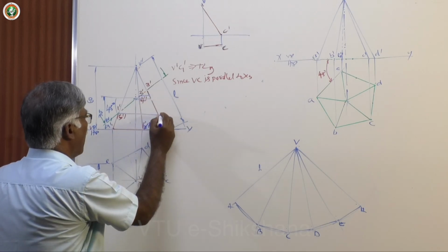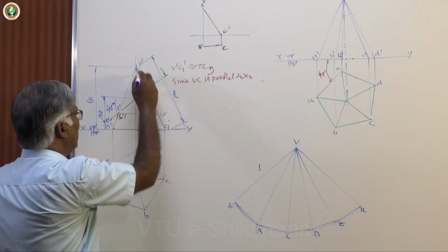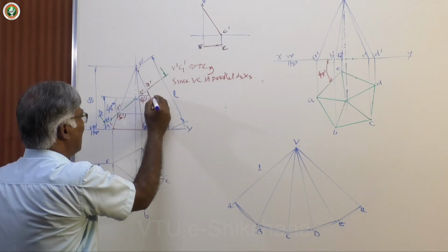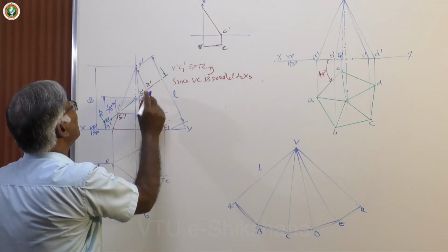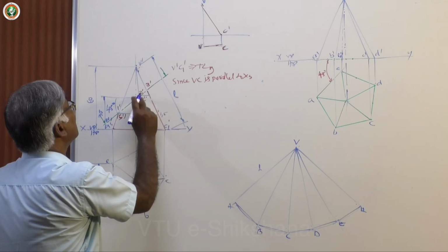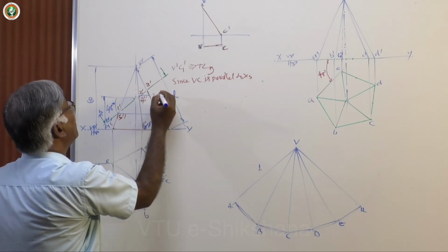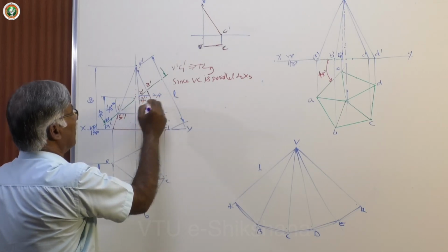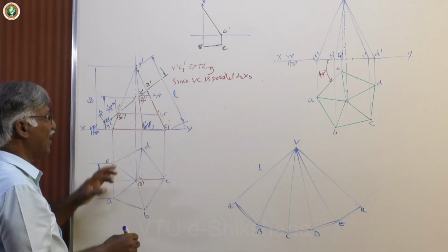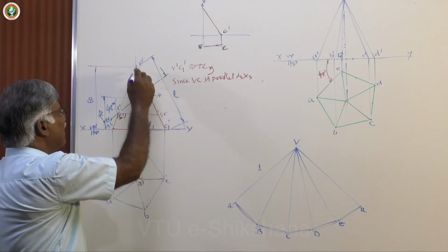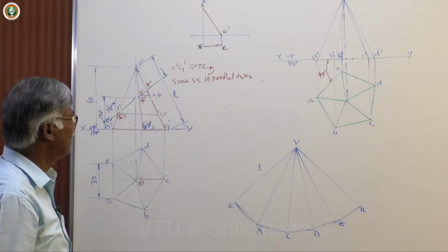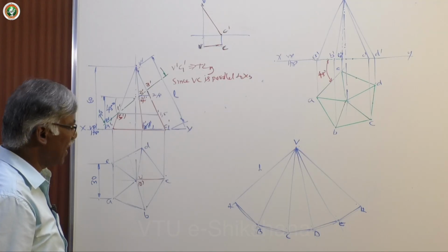So, here is 1, 5 true length V1, V5, instead of taking this you have to take. Here is 2, 3 axis line, it is not a problem, here is one more, this is 2, 4. You can keep 1 dash etc., not necessary. Here 3, that itself is the true length, 3 dash. Okay. Now, start working.